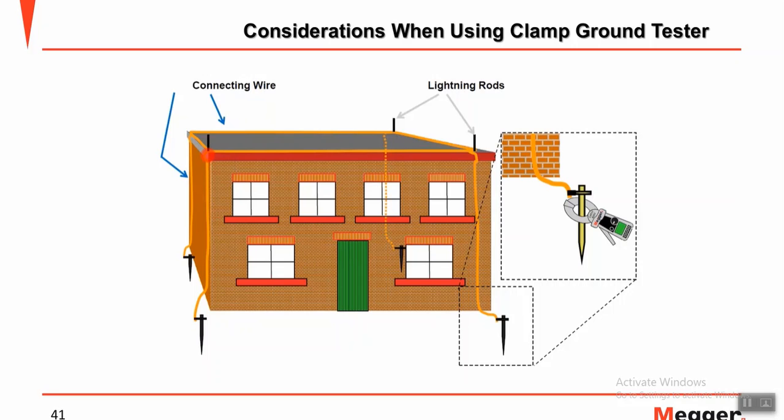So as per Ohm's law, you are just measuring the resistance value of this bar, not the actual ground resistance value. Yes, you need to make sure the ground electrode is connected directly to the soil.